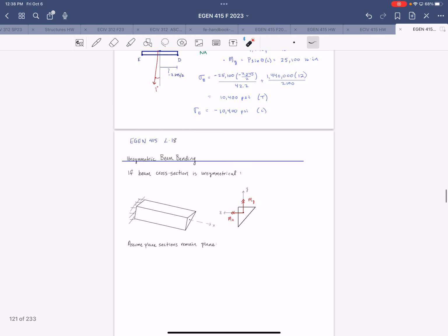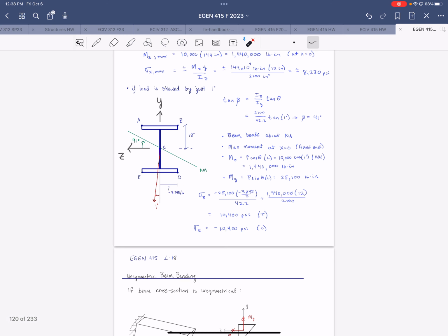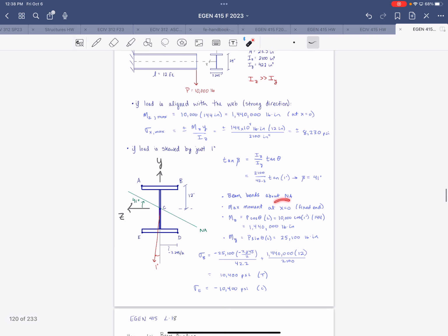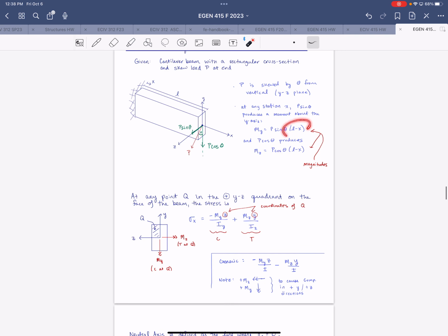So then x would just be the distance along the beam that you're evaluating, like in our previous general terms. You mean where I say x equals 0 here? Yeah, like when we do the L minus x portion of the moment. Oh, yeah, for this general expression. That was specific to this configuration, but we always take x as being measured positive from 0 at the left end.